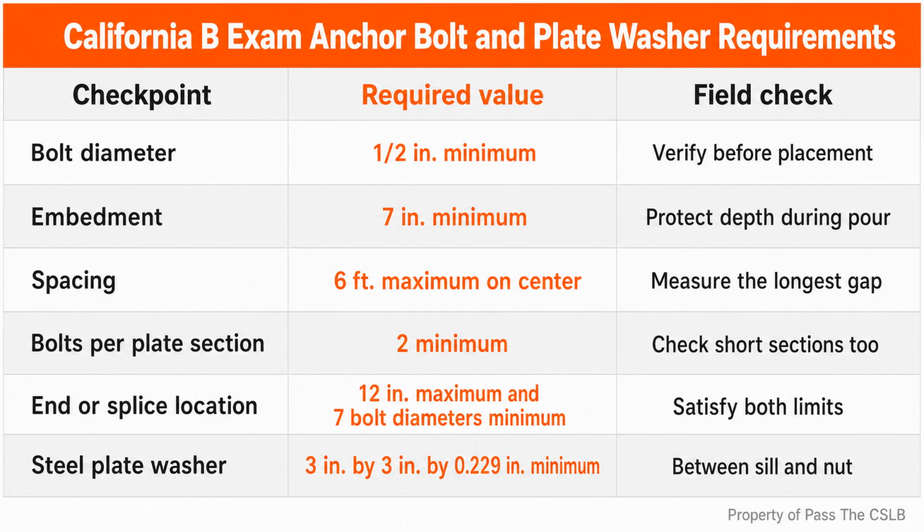The field supervisor should check the batch ticket, arrival time, revolution information, approved mix requirements, and project procedures before discharge. If a load is outside the permitted limit or its condition is questionable, I stop placement and resolve it through the responsible supplier and project requirements. I do not let schedule pressure turn an expired or unverified load into concealed concrete.